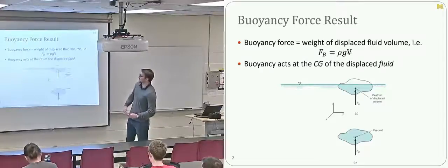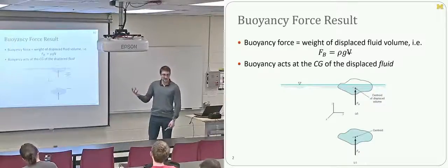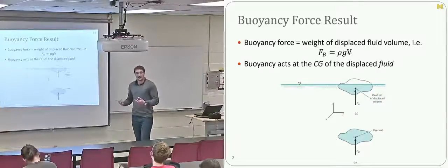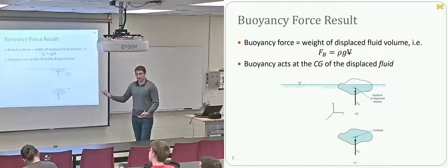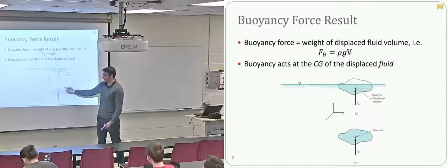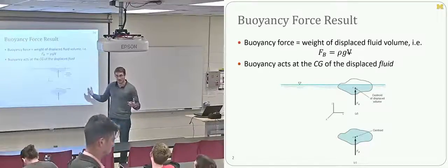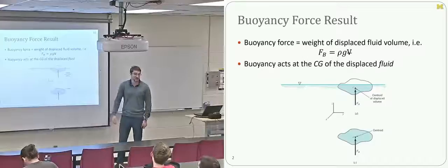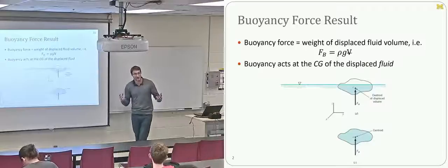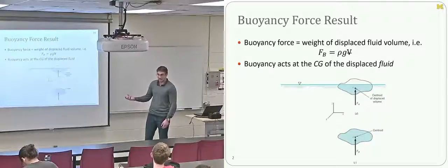The idea being, if you have a fairly homogeneous piece of material, let's say it's a piece of plastic, and you throw that into a pool, its density is going to be constant everywhere, whatever is displacing the water, and as a result, if it becomes fully submerged, then its own geometric centroid and the centroid of the volume of the water it's displacing will be concurrent, they'll be at the same location. Which is why if you take something that doesn't have any particular distribution of mass, then it doesn't care what its orientation underwater is, right?